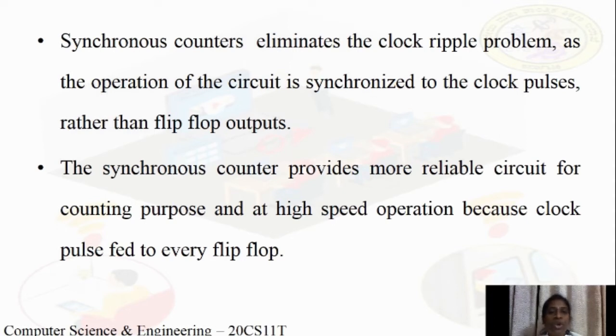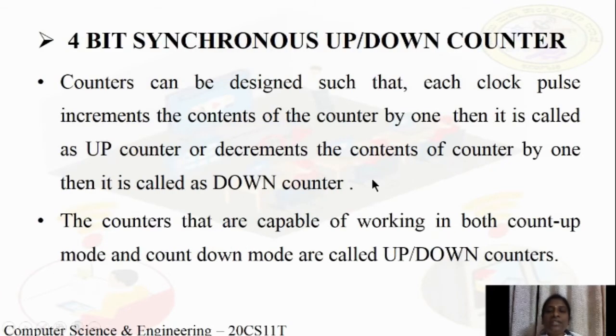And these synchronous counters work with a high-speed clock, because the clock pulse is provided to all the flip-flops simultaneously. This is about the synchronous counters. Please remember, in the synchronous counters, the clock pulse is given to all the flip-flops at a time. So it is a reliable circuit and the operation speed is higher.